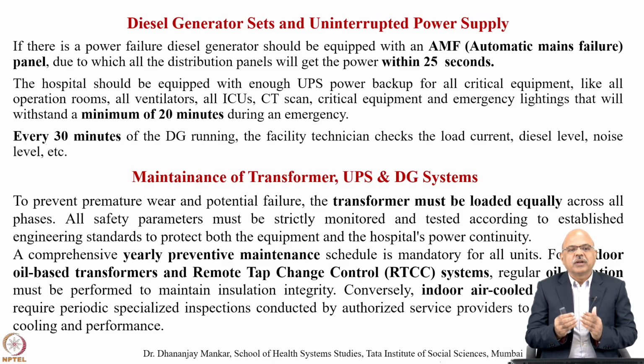Due to which all the distribution panels will get the power within 25 seconds, which is very important for those conditions which are more dealing with critical operations. The hospital should be equipped with enough UPS power backup for critical equipment like all the operating rooms, ventilators and ICUs, CT scan, critical equipment and emergency lighting that will withstand a minimum of 20 minutes during an